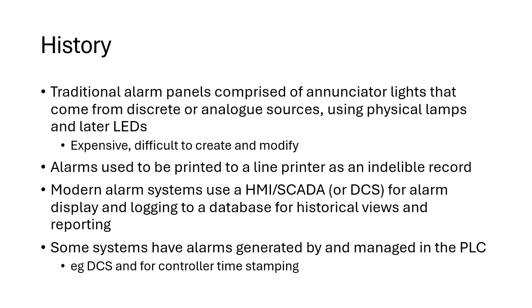So in modern alarm systems, we use a HMI SCADA or the operator screens of the distributed control system, and those are used for alarm display. And in parallel, we also log to a database so we can have historical views and reports. And this is all done electronically on modern computer systems, which makes it much easier to handle and manage the alarms.